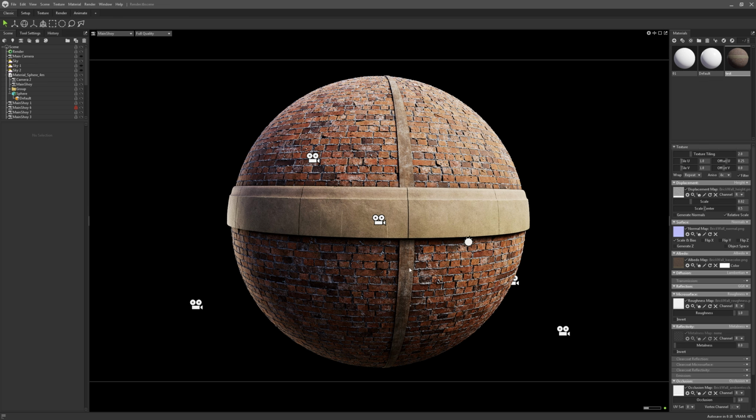Now, if you see that your base color looks a little bit whitened up, that means you have it in linear RGB, and you need to have your base color in sRGB. So make sure about those two things so you don't have any problem. Now for the metallic, in this case we're not using anything, so we're going to have it at 0.